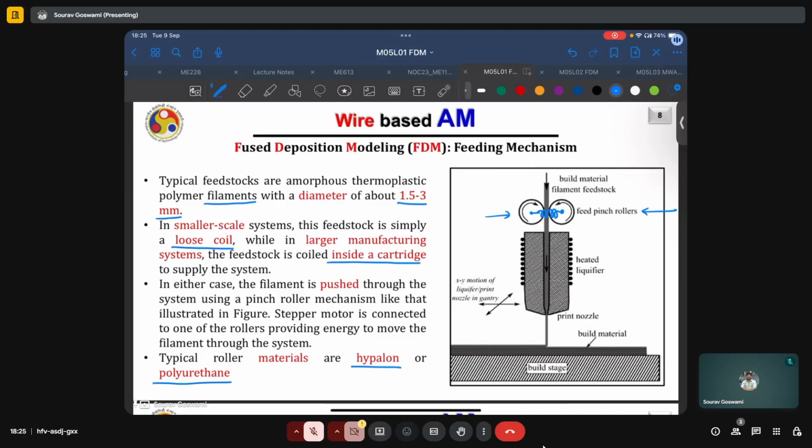Here we see that the build material is being fed from some roller or some wire spool. The spool also imparts some tension to this wire so that it does not uncoil all at once and is fed only at the required rate. Typically at the start of print, or while being commissioned, the machine will be calibrated. But even then, periodically what we would want to do is calibrate these rollers, which is to check whether they are supplying or feeding the wire at the desired rate.